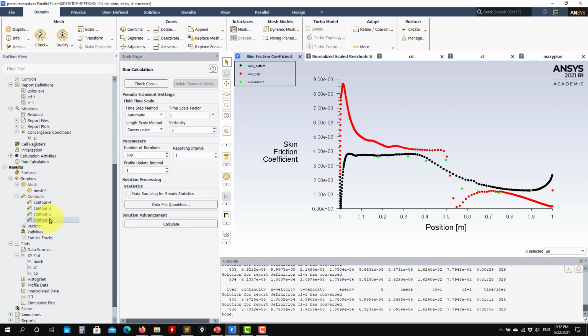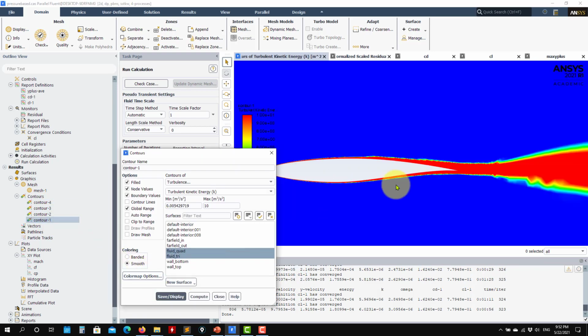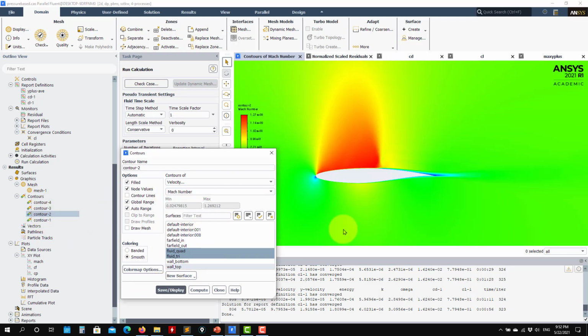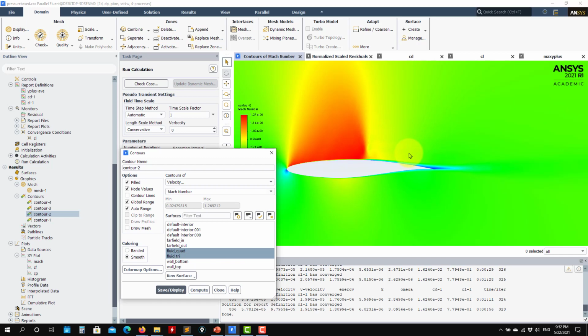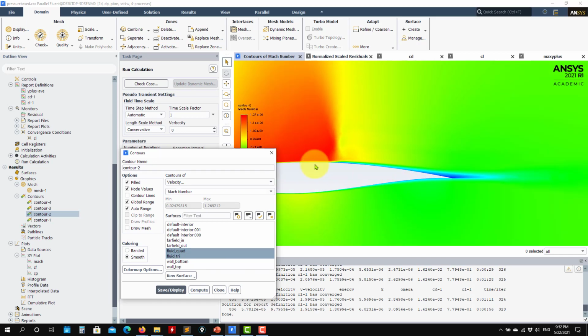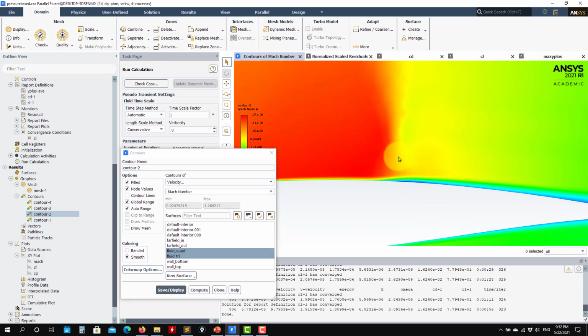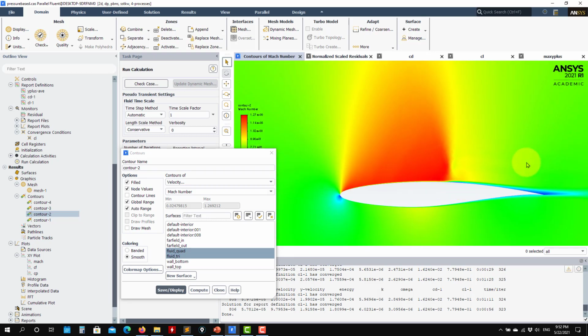Again, finally, remember that you can plot the normalized velocity profile, okay? So let me go here. So you can pick a line and plot that, okay? So you can plot it here or here. Avoid plotting in the precise region where you have the shock wave, okay? For obvious reasons. But you can plot it here. Remember, it has to be where the flow is fully developed and fully turbulent, okay? And you should be able to get the similar, theoretical profile.